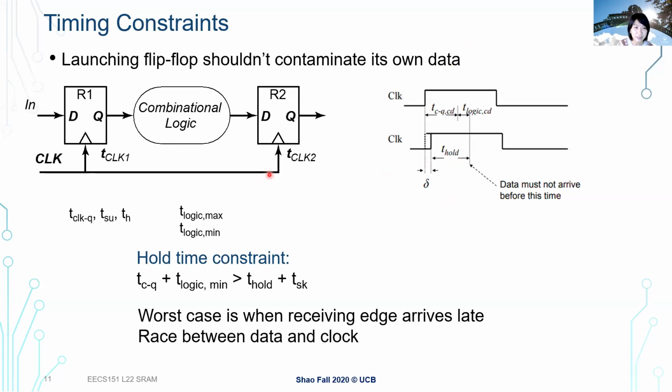For small scale, like in this fairly artificial example, the values are actually pretty close. But at really big scale, when we talk about a clock distribution network with all the different wiring and buffering being inserted, sometimes it can make a significant difference. So it's really important to keep in mind that delay is not only the signal delay, but you also need to consider the non-ideality of your clock when you put the different contributing factors together in the timing analysis.